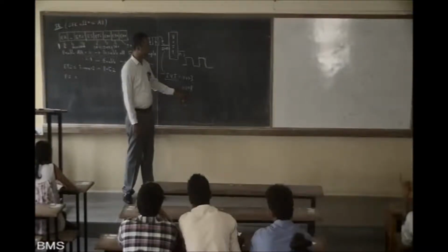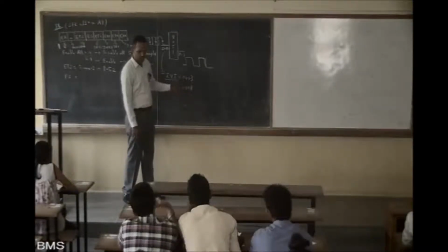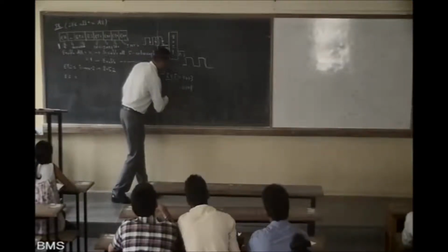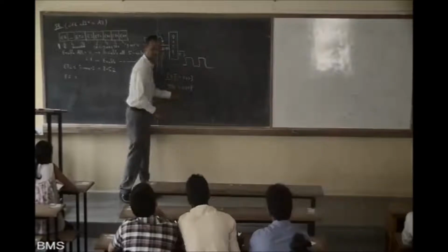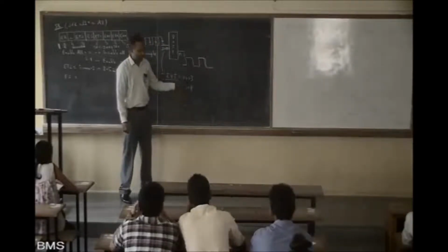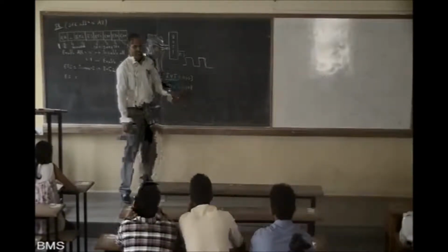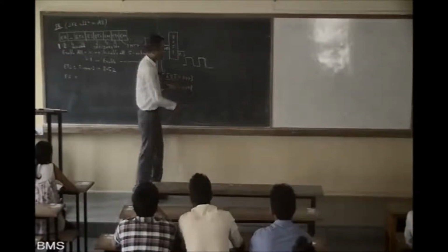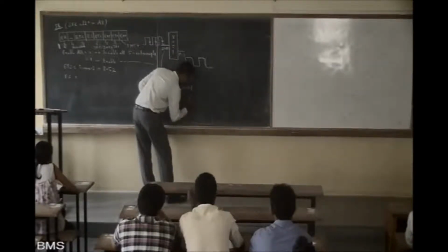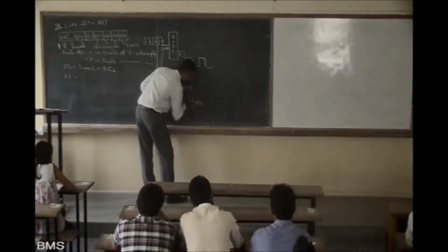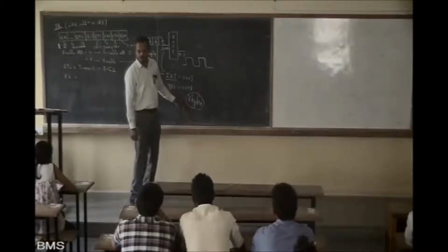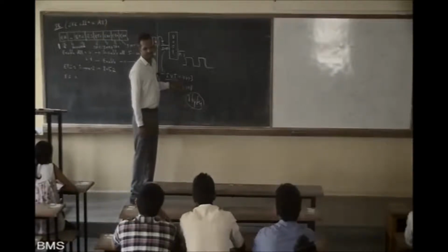What is the next thing after this? The TF0 IVT address is this. Correct, right? Next address I wanted. 3 to B. B is what? A, B, 11. 11 minus 3 is 8. So there are 8 bytes of space available for you to write a code, a code which runs an interrupt service routine.